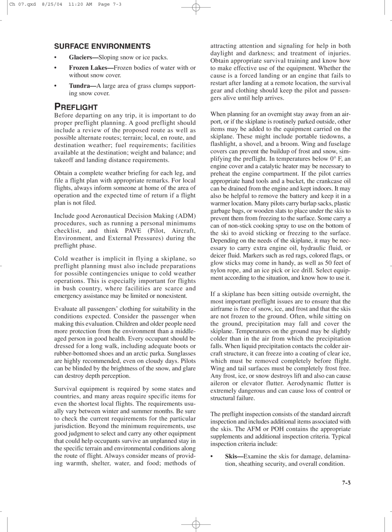Cold weather is implicit in flying a skiplane, so pre-flight planning must also include preparations for possible contingencies unique to cold weather operations. This is especially important for flights in bush country, where facilities are scarce and emergency assistance may be limited or non-existent. Evaluate all passengers' clothing for suitability in the conditions expected. Consider the passenger when making this evaluation.